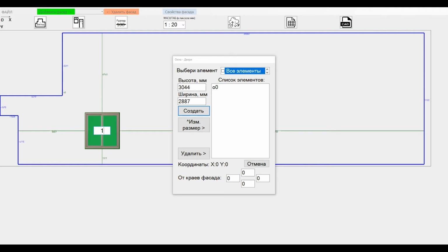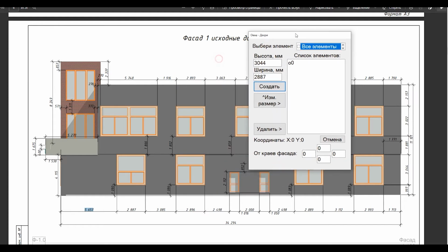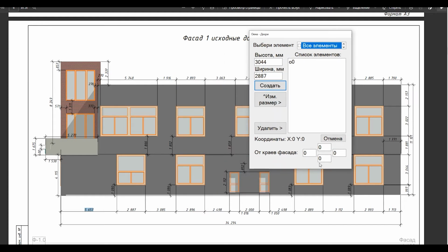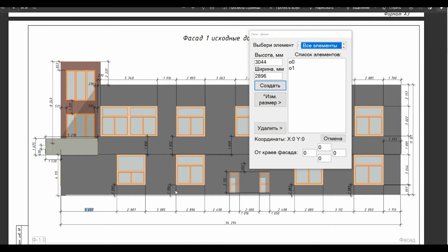On the dimension lines you will see how far it is from windows and floors. Here I put 1090 millimeters to the floor. So drag this window frame, and then check the dimensions of the other window. Here we need to input the proper sizes. Click create and repeat the alignment towards the windows and floors,